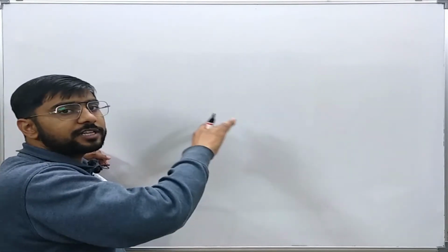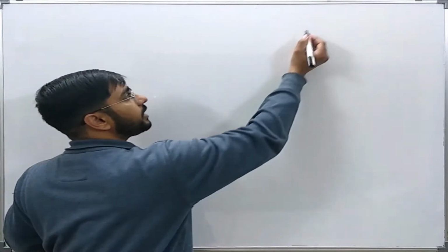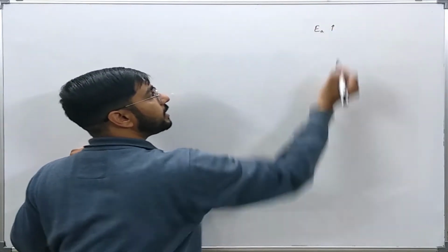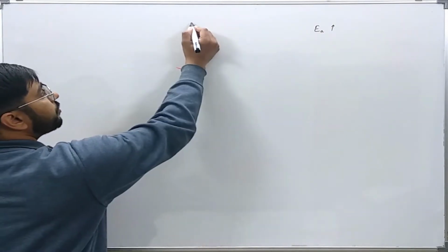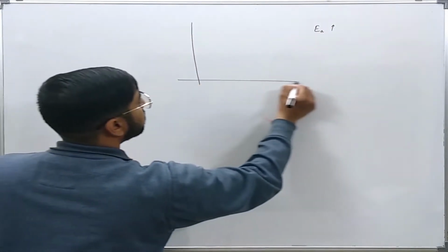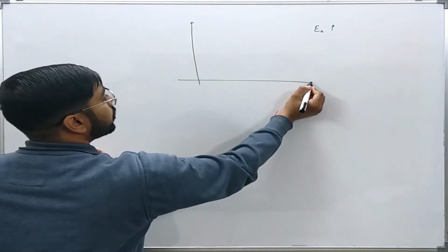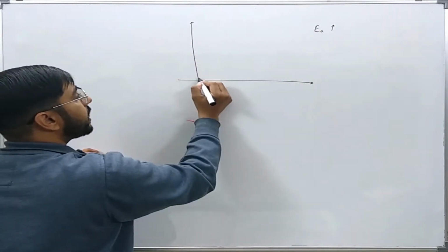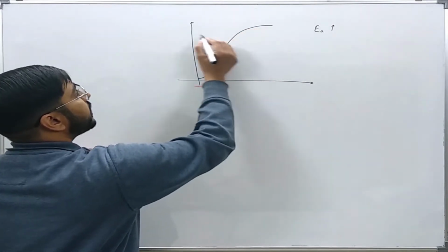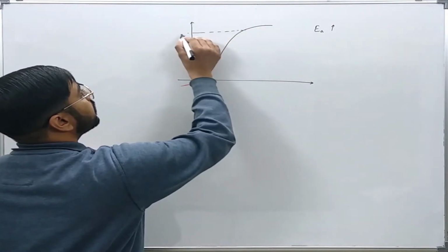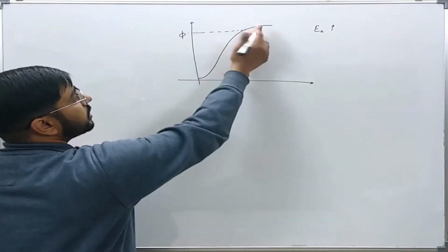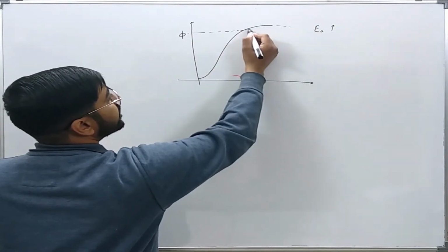Or if the burden is very high, so that the induced EMF EA is high in the CT, then we can see from the excitation characteristics that to get this higher EA, the flux required will be higher, and beyond the knee point, the flux requirement will cause the CT to go into saturation.